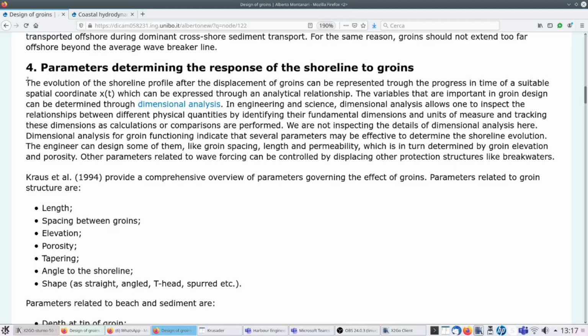Now, we talked about limits to the coastline, and groins are precisely a kind of those limits. If we put in the model we just developed a barrier perpendicular to the shoreline, it means that when we reach that barrier, the sediment transport goes to zero.